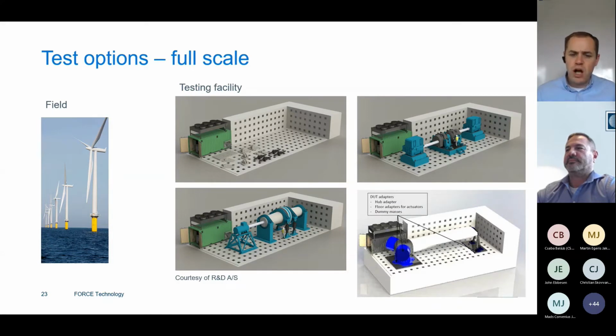It's about building up the test program that's required. And the other test possibilities are, in this case, also trying to show components from a wind turbine that can use this endurance testing, lifetime testing, where we're looking at possible fatigue aspects happening. Upper right would be a back-to-back gearbox test. Bottom left, looking at the testing of a main bearing from a turbine, and bottom right, the testing of a pitch bearing from a turbine.